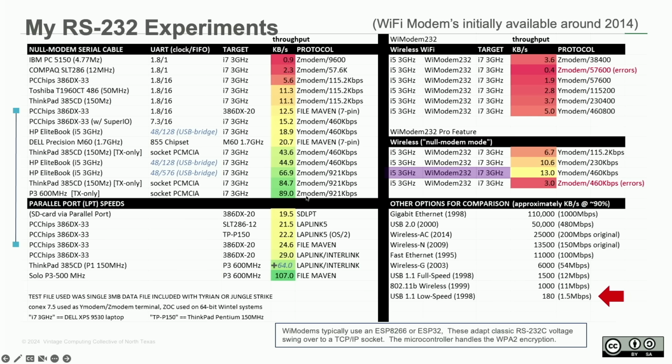So whatever's in that PCMCIA card, it was able to do it. The USB cables I was just showing were good. It was only 66.9, so it's not doing the full 921. It's definitely beating 480. But that's using a high-end computer, a 3 gigahertz to a 3 gigahertz machine, cheating through USB. But it is using RS-232 to do that speed.